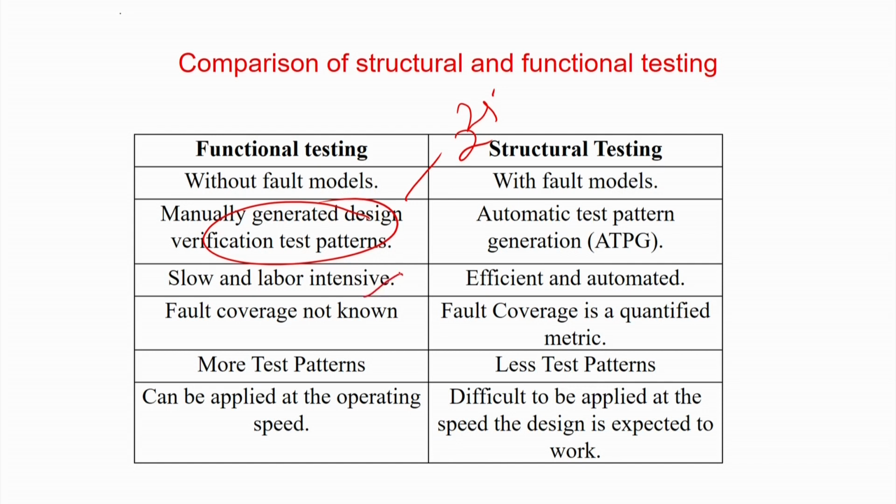Slow and labor intensive, fault cover is not known, more number of test patterns and cannot be applied at the operating speed. So, those things we will see later, but the idea is that it is a huge number, and in fact, if you want to reduce it, you have to manually find out which are the most important test patterns.